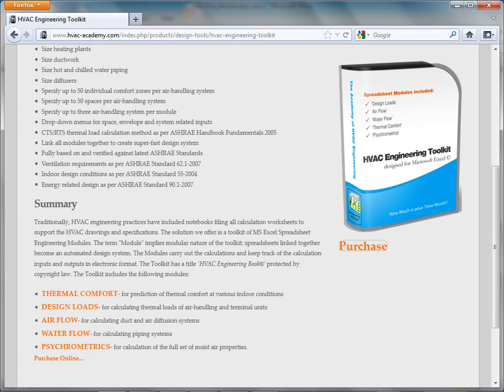This schematic represents a general air conditioning concept of the building that is usually prepared at early stages of HVAC design by the project engineer. The concept determines general arrangement and interaction of the HVAC equipment and sets forth the HVAC design scope. A central air handling unit shown in the dashed rectangular shell supplies a constant volume of conditioned air to the occupied spaces via ductwork.